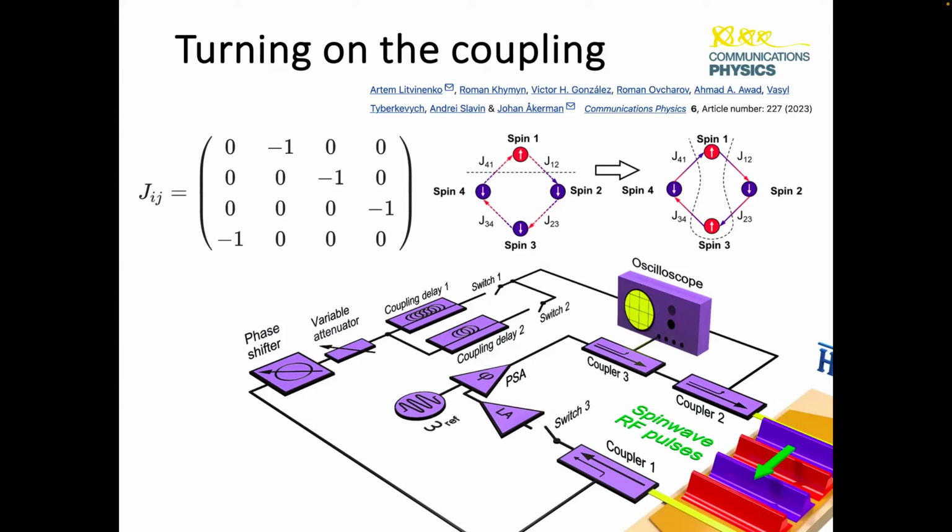And the way we implement this coupling is not with FPGA. This is our very first attempt, so no FPGAs at the time. Instead, we're going to have a coupling cable here that is some 20 meters long, and it has a delay time of 68 nanoseconds, which corresponds to 1 pulse moving 1 step, the pulse train moving 1 step.